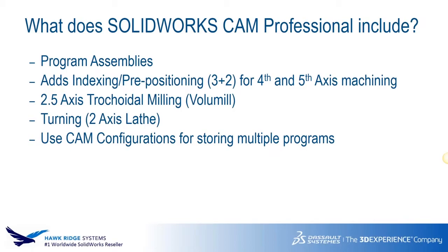So basically if you're using drip feeding to communicate to your machine, or you want to send the programs rather than using a USB key or anything like that, if you've got it wired up and you're sending code to the machine from your computers, basically there's an NC editor that allows you to do things like backplotting of the toolpath itself, so you can verify the G code that's coming out of your post. It will do the DNC setup to your equipment and a bunch of other functions as well. Things like edit capabilities, change sequence numbers, show you where the tool changes are, and things like that. And that's all included in the CAM standard version.